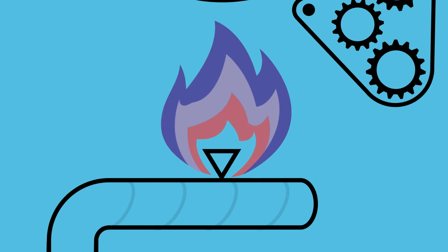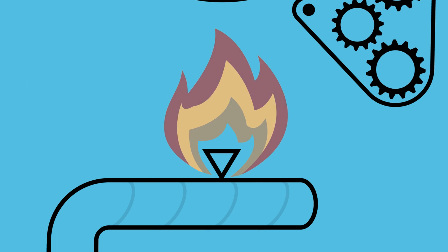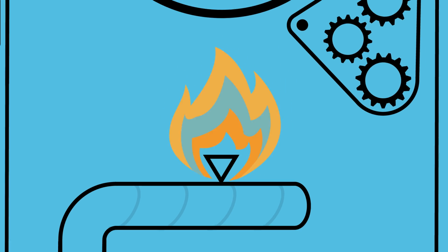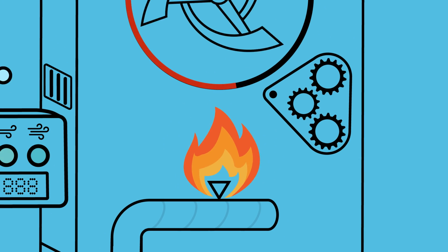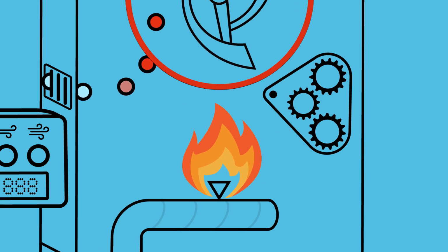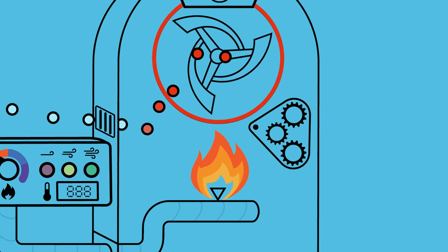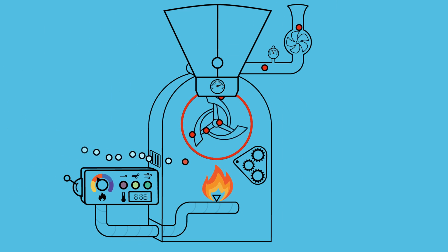But understanding how much BTU bandwidth you have and how that is going to be an input into your coffee is fundamental to understanding how quickly or slowly you need to roast your coffee, or that you can expect that coffee to go through the roasting process. So that heating element that you have in your roaster is designed to either heat the drum or heat the air or heat all of the above. Most cases it's there to heat all of the above.